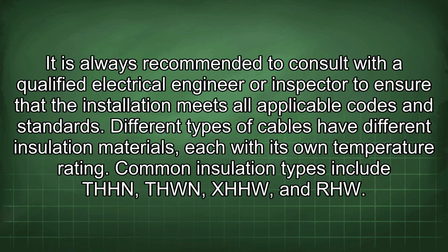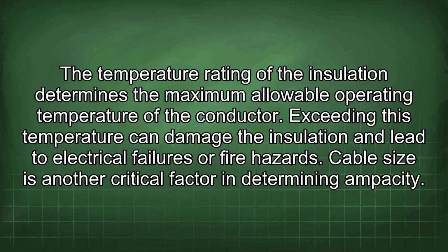Common insulation types include THHN, THWN, XHHW, and RHW. The temperature rating of the insulation determines the maximum allowable operating temperature of the conductor. Exceeding this temperature can damage the insulation and lead to electrical failures or fire hazards. Cable size is another critical factor in determining ampacity.